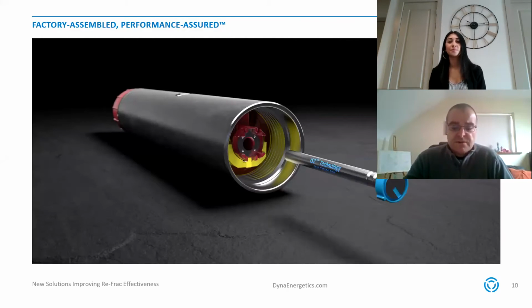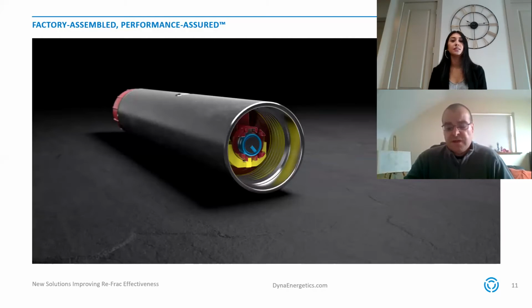Once installed, the complete plug and perf string can be fully tested before running in hole and also while running down hole until the gun is initiated. Intrinsically safe detonators are a vast improvement over standard addressable switches and resistorized detonators, allowing uninterrupted communications and are immune to unintentional initiation, for example, by stray voltages, stray currents, or high frequency communication devices, or even megavolts.